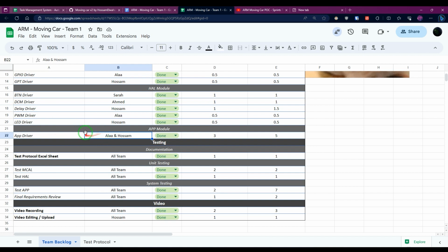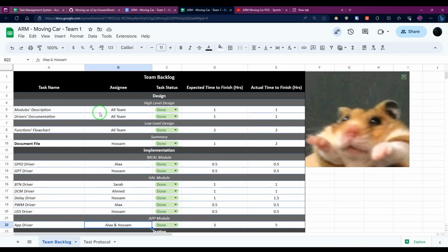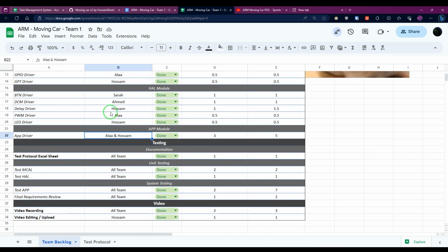The application implementation wise was easy to do, but when we got to the hardware, we faced some issues, especially finding the appropriate PWM period, which we ended up with 10 microseconds, which works really well with our DC motors. As well as the duration for the rotation, it's currently set to 500 milliseconds, but